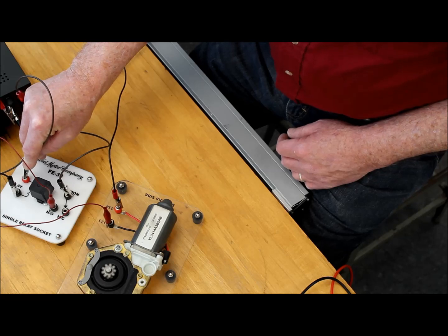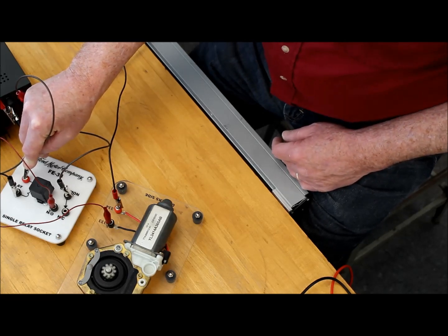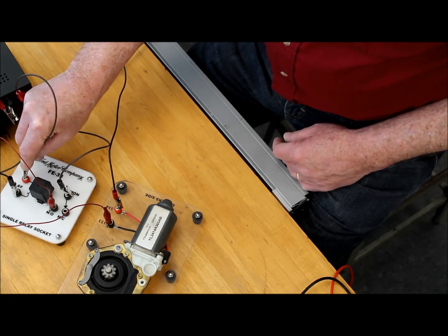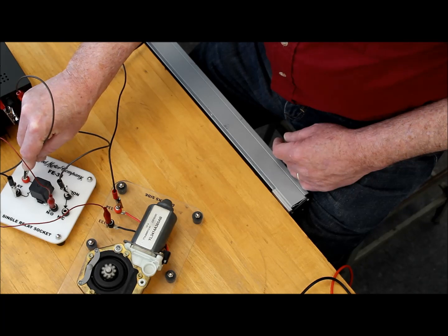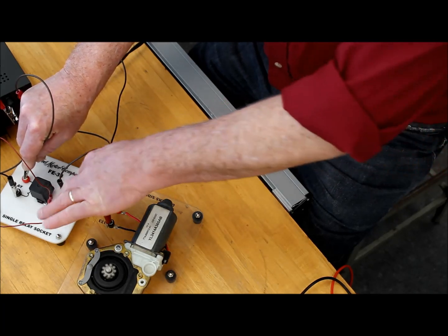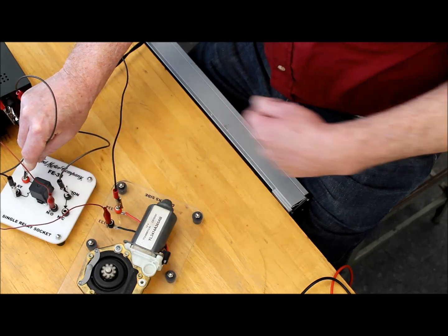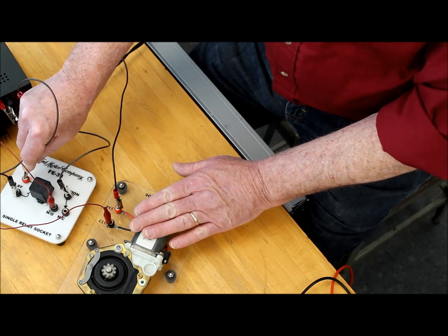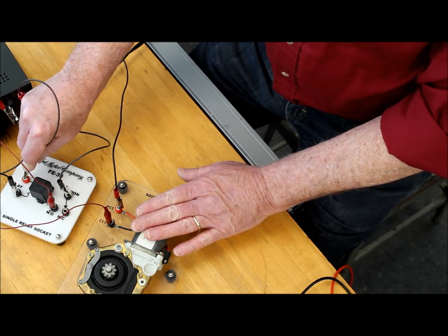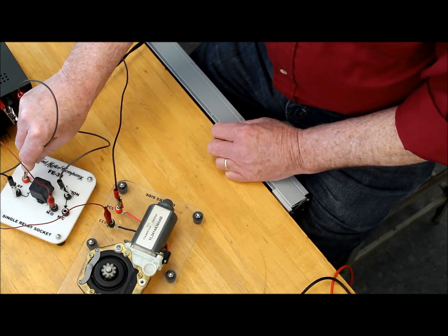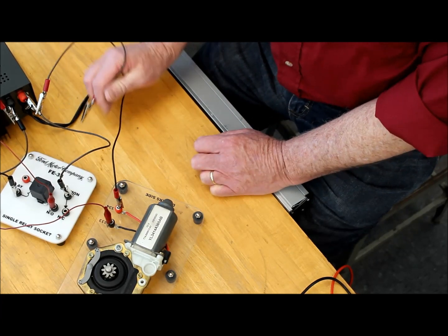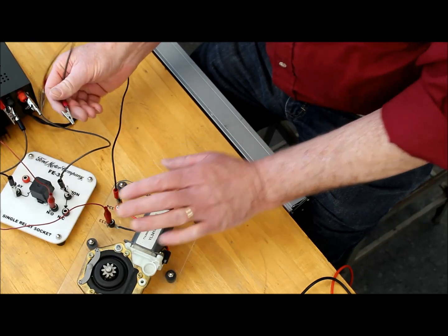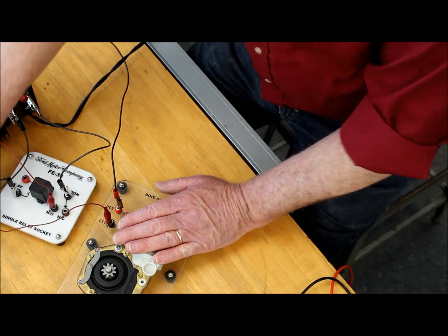So you know the relay coil only takes 0.18 amps to operate, but by using that 0.18 amps to energize the relay, when the relay closes, the contacts inside the relay on the load side provide current to the window motor, which is taking, we know, between 3.5 and 4 amps, and that's without a window on it. So this is called indirect control. This is how a computer can send a small amount of current through the relay coil and control a much larger amount of current, like through this motor.